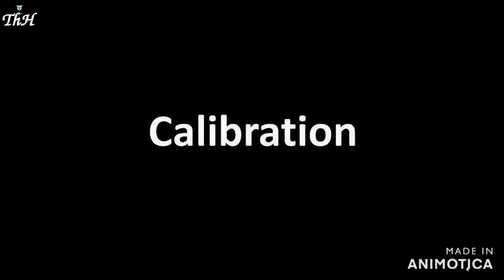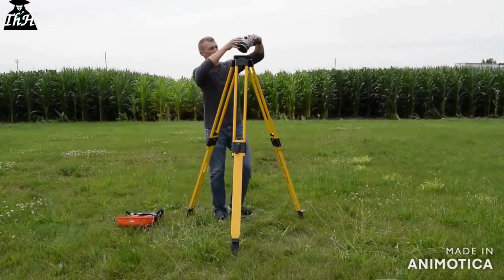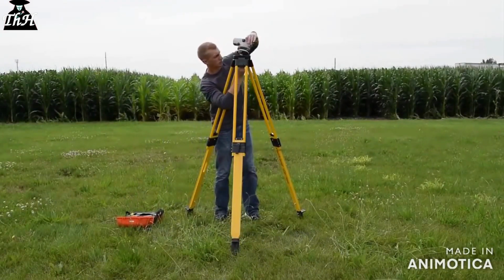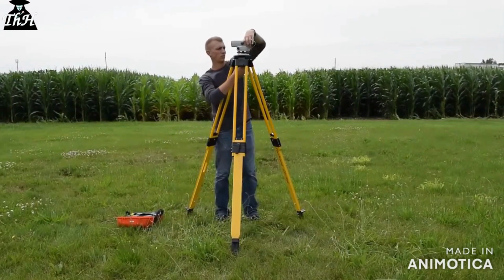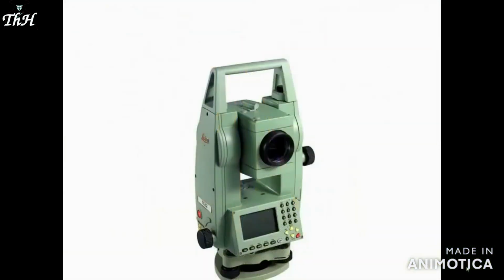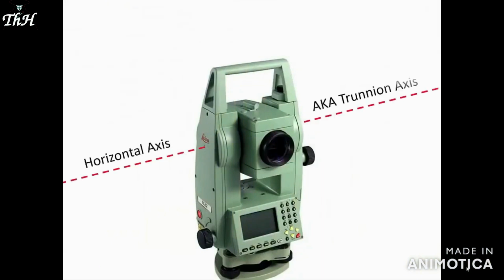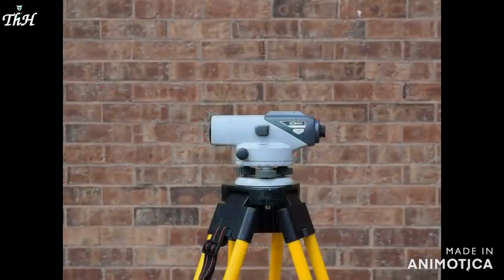Every optical surveying instrument requires periodic calibration. Internal wear and tear caused by normal use and handling can slowly degrade instrument accuracy. Calibration includes carefully analyzing the instrument's accuracy and, if needed, adjusting it to restore degraded accuracy. Complex instruments like this total station may require calibration by a trained specialist. Common automatic levels can be calibrated by an experienced user.